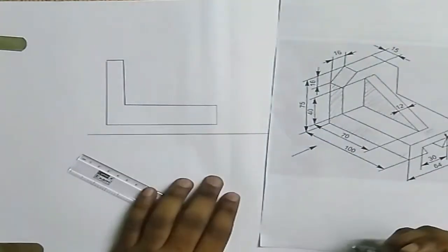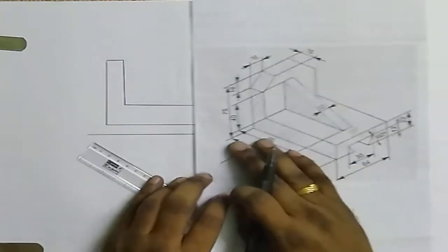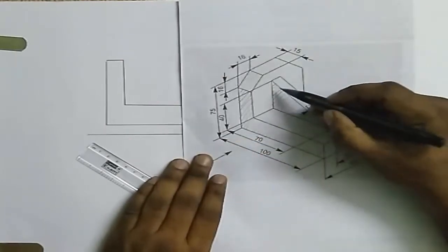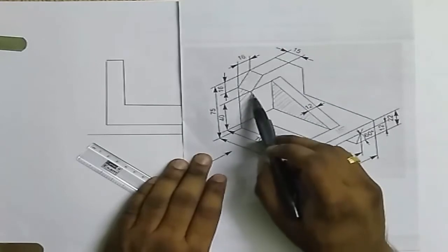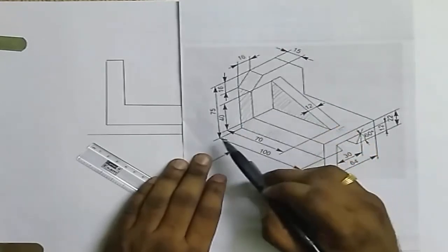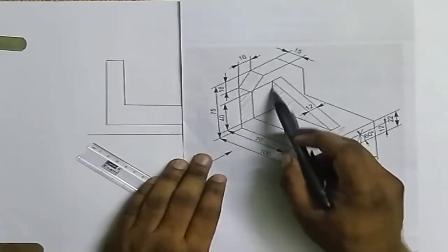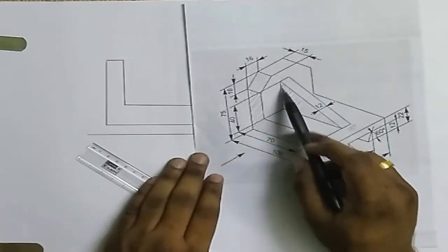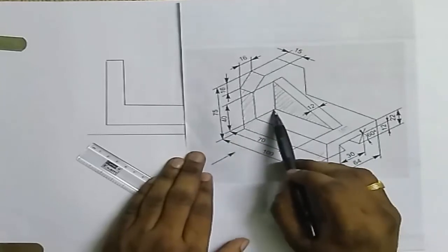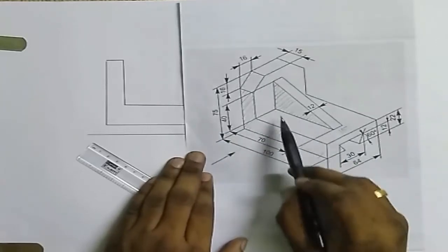So this is the first rectangle I have drawn. Then you have to draw this portion. This shaded portion has to be drawn. This shaded portion, this line and this line, from the front view, these two lines will be coincided. So from here the height of this line is 40 mm and the horizontal length is 70 mm from this